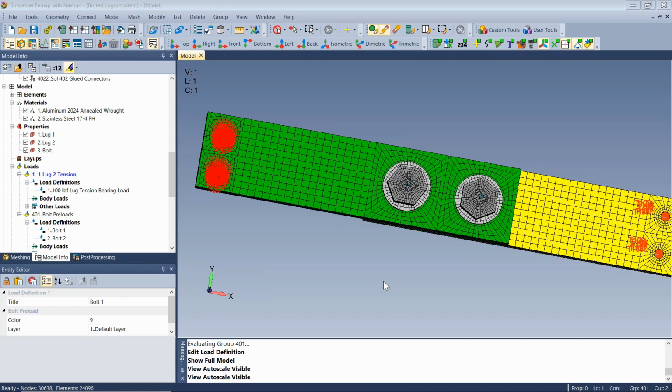It's almost like you're gluing them: pushing them together and gluing them, and they can't come apart. Sliding glue means they're basically in compression, and they can slide relative to one another, but they can't come apart. So that's the difference between no separation and sliding glue.